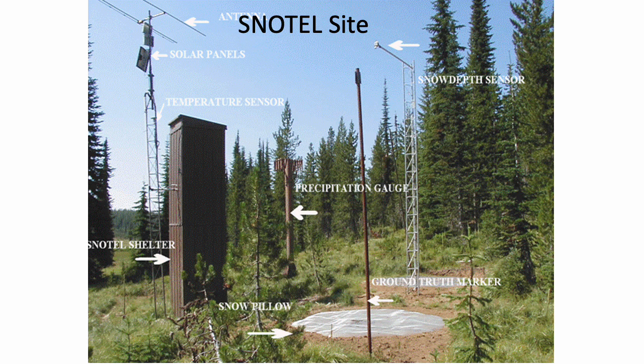You might have a snow depth sensor, which is an acoustic sensor, kind of a pinger in a sense. It sends out an acoustic signal, and the amount of time it takes for that signal to get back up to the sensor tells you the distance from the sensor to the surface of the snowpack. It's kind of the way that some cameras work. There are also temperature sensors there, and occasionally additional sensors like relative humidity and incoming solar radiation. You can also see that precipitation gauge back there, the thing that looks like a rocket launcher with the Alter shield around the top of it.